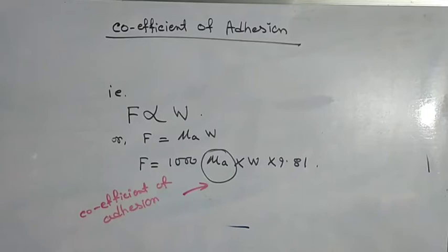Now, with DC locomotives, since the DC motors are light, it is desirable to place the whole of the locomotive weight on the driving wheels to obtain the required tractive effort, whereas with AC locomotives, since the weight of electric equipment is higher, the required tractive effort can be obtained by placing only a portion of the weight on the driving wheels and supporting the rest on the trailing axles.